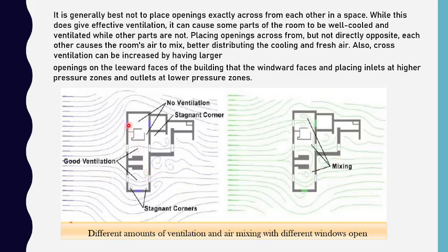Both the pictures are quite similar, and in this picture you can understand how we are having a mixing of wind. We have 3 openings on this wall through which we are able to get fresh air, whereas we do not have much of the cross ventilation over here, as these 3 walls do not have any kind of ventilation, or this particular room is also not having any kind of ventilation, because of which hot air is being created over here. Overall, if at all we are taking this plan, then we are having mixing of wind. In the sense, cold air is mixed along with the hot air. So as an architect, we should try our level best to have a cross ventilation while designing a building.